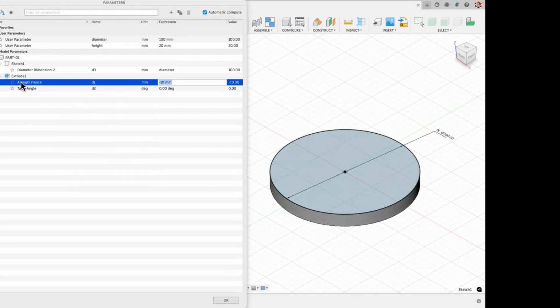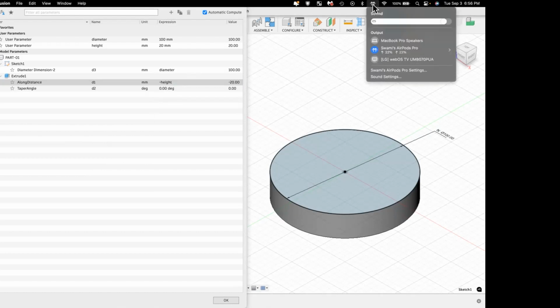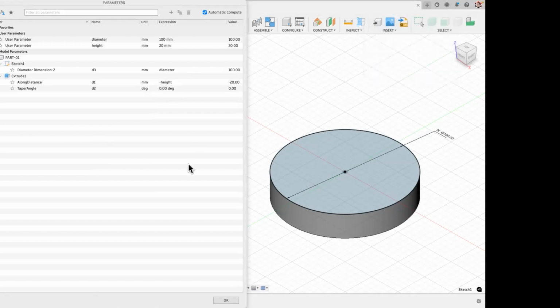And let's do the same thing for height. Plus, H-E-I-G-H-T. Let's make this 20 bigger so we see a change. Tab twice, 20, enter. And then we apply it. Now I went negative. This one was the extrude, we went -10. If I can do it, I often like to go negative so I can still see the sketch on the top. It depends what you're doing. So type negative height, negative HEI. And now it's going to be 20 instead of 10.